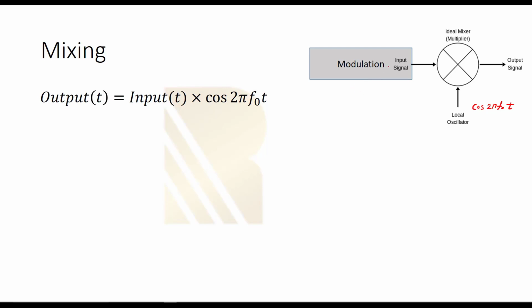So we always have to modulate our data. We never directly send the data to the mixer. Generally, in most of the structures, we are mixing the modulated data, which has IF frequency. After this modulation, our data has a channel, and here we have an IF frequency, for example. And here we are trying to upconvert from the IF to RF. So this part we will have RF. It's very important to know that this part we will have a modulated signal.